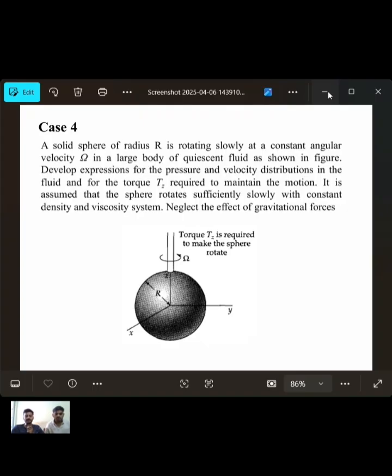And here we are assuming laminar flow, and this vortex formation cannot occur in laminar flow. So this kind of thing comes under an unsteady state assumption. For ensuring no vortex formation and only steady state, we should have a very small omega and a non-viscous kind of fluid, and we have to ensure that.